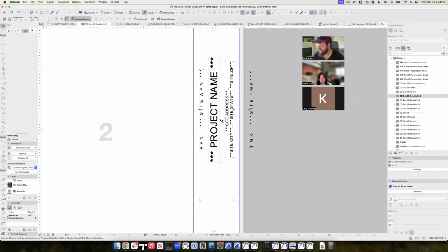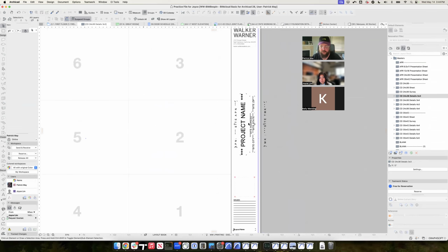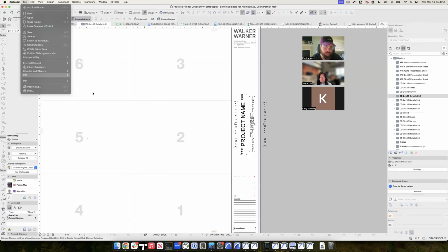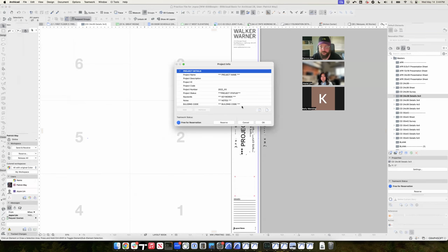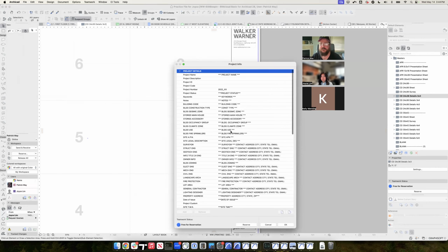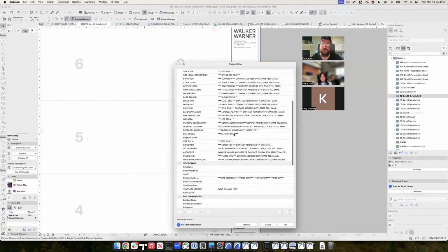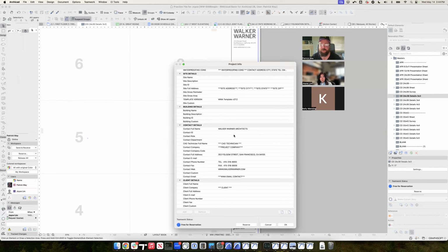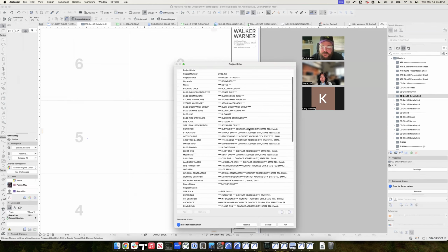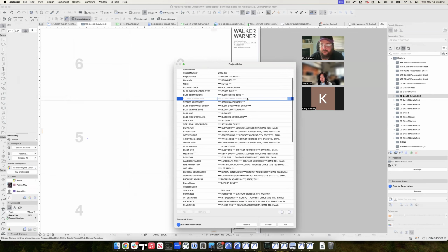And this gets into the information management section, so we can go ahead and sort of incorporate these together. But things like the site address, project name, APN, TMK, whatever project information, all of that is stored under File, Info, and Project Info. And this is stuff in any project, anything with an asterisk, you're going to want to fill this out as you know it, basically. So if we don't know exactly how many stories are in the house to begin with, that might stay blank.